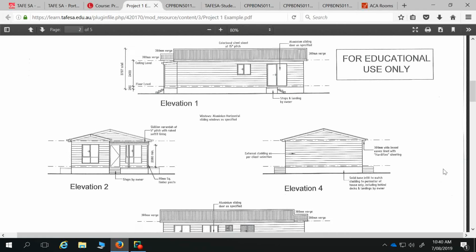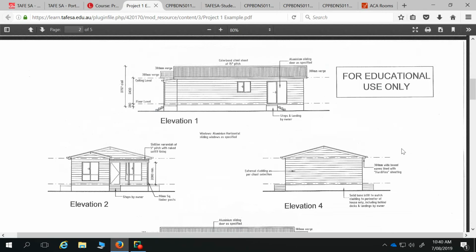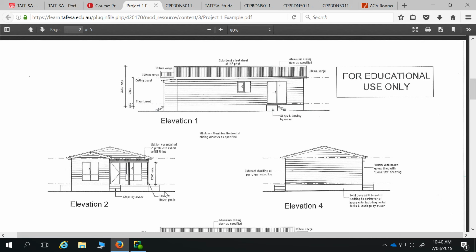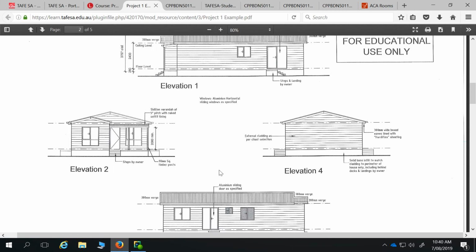Elevations. So for elevations, again, you can see they're quite simple. They're showing the fenestrations on the building, so openings, the roof material shown by illustration and a bit of annotation there, and also the cladding: weatherboard is shown by having that horizontal hatching pattern, and obviously our levels. And part of what they want in the Resi code is an overall height of building as well. So that's one of the things that you have to tick in the Resi code that you've got shown on your drawings.